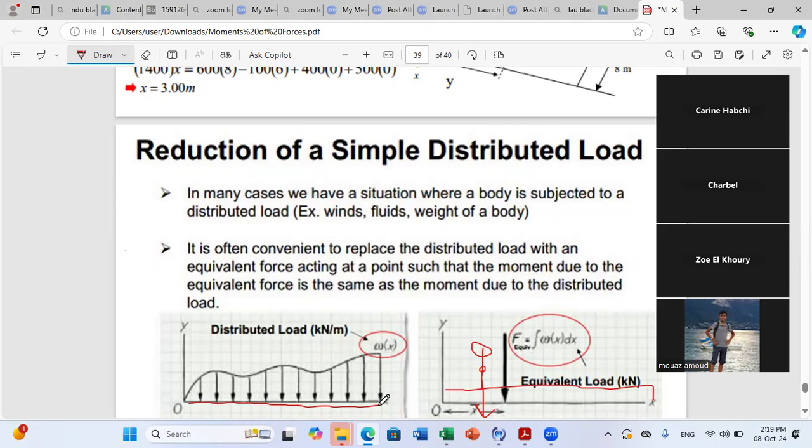First, plus we'll see together here that when a force and a couple are perpendicular, you can move the force in a way to produce the same couple. Then you don't need to represent your system by a force and a couple. You can reduce your system to one single force. So keep in mind, we have particular cases where we can reduce the system to one single force, okay? This is the case when you have the force and the moment perpendicular to each other. To understand better what I am talking about, I'll give a simple example, okay?